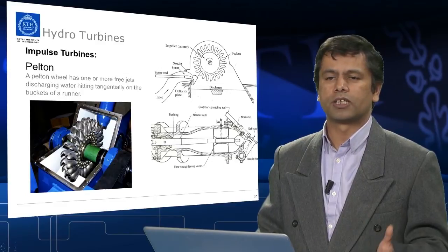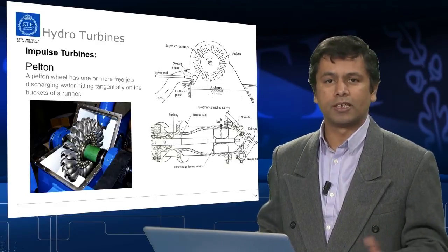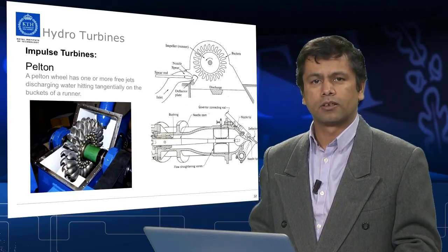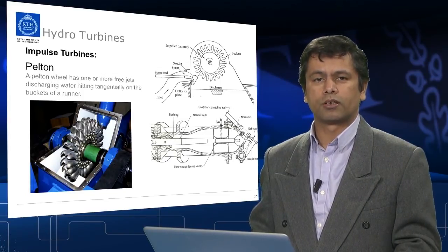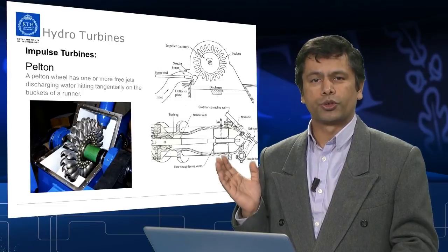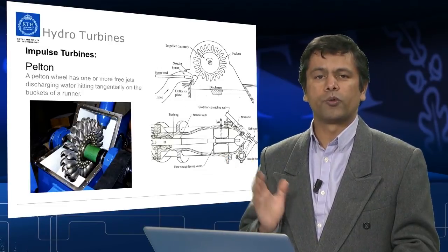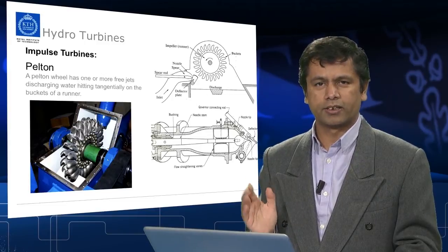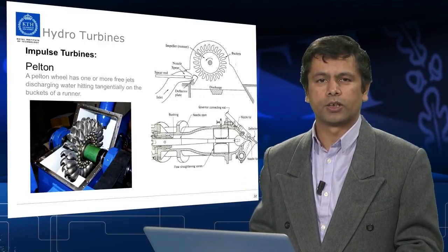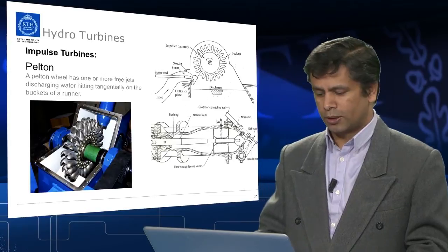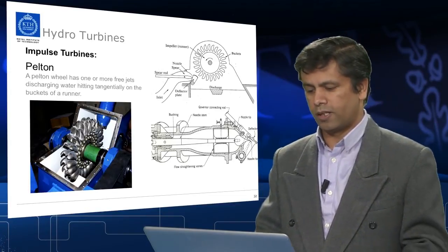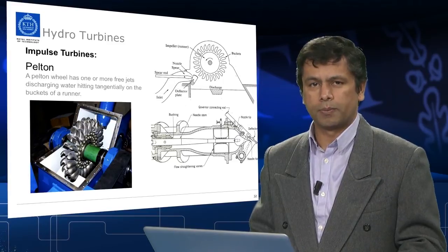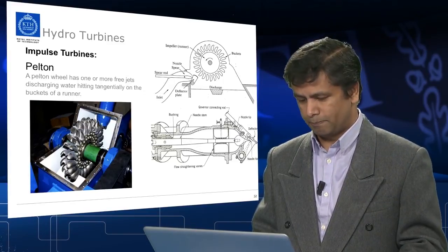If there is a sudden change in the voltage or speed in the generator, then the function of the deflector is to actuate and control the flow, so that the flow will not strike the bucket but strikes the deflector, and the water will drop down to the tail race without moving the turbine. So the main purpose is to save the turbine from going over speed during an emergency.